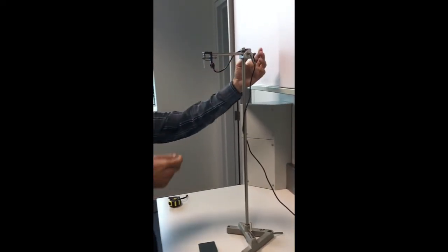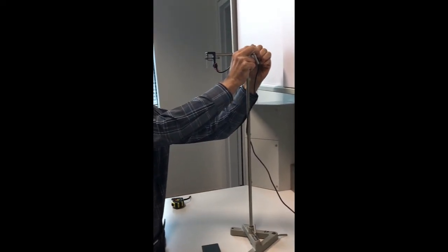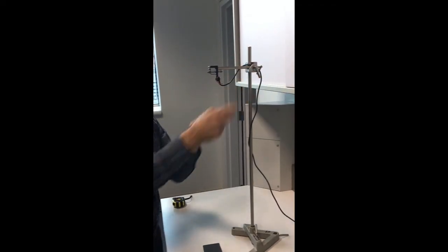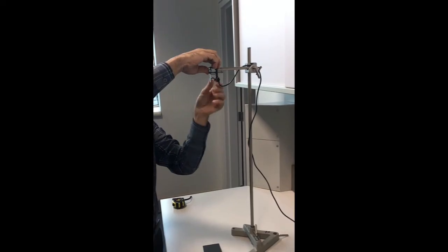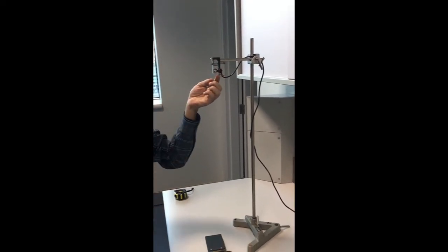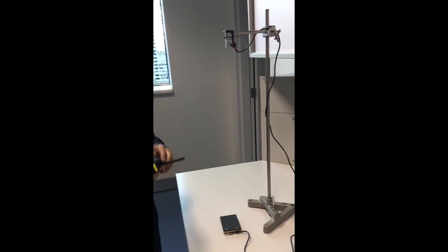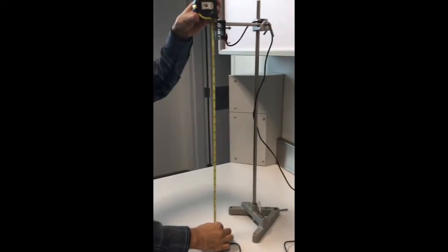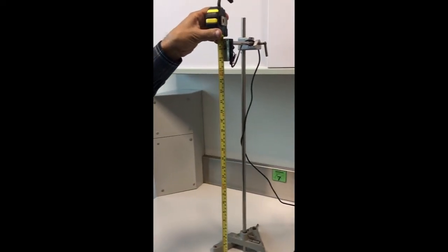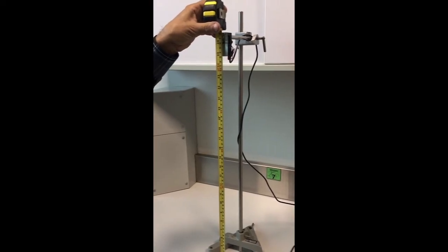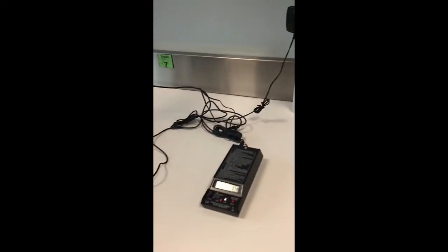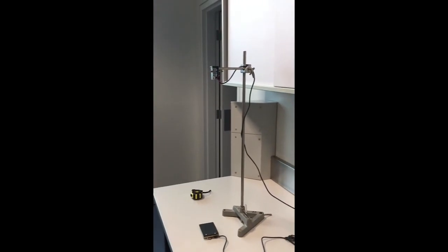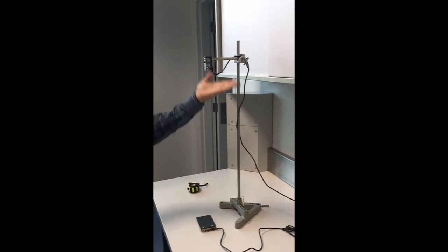Now I'm going to change the height by loosening this screw that holds the assembly in place. Change it a little bit. And then put my sphere again. Now the distance between the bottom of the sphere and the top of the pad is measured again. Now it's gonna be a different value. As you can see here, it is now 63, exactly 63.0 centimeters. And then you repeat the same process again. The sphere will be dropped from this height 3 more times, okay, 3 times. And then you take the average, then you change the height once again, and so on.